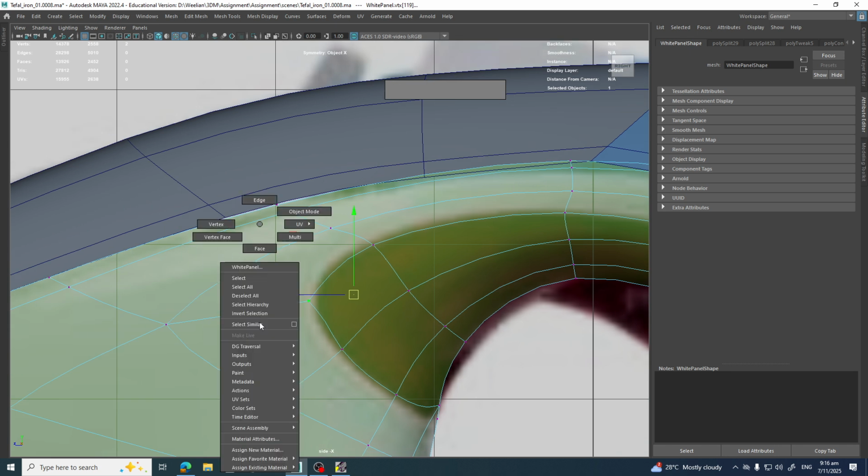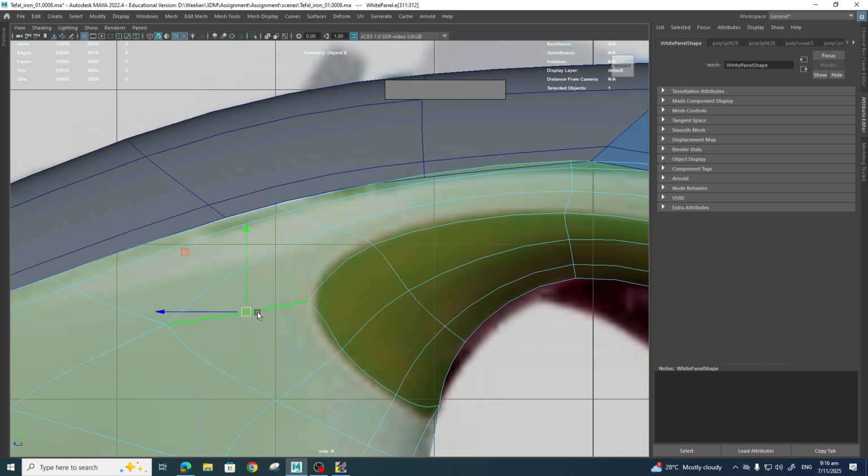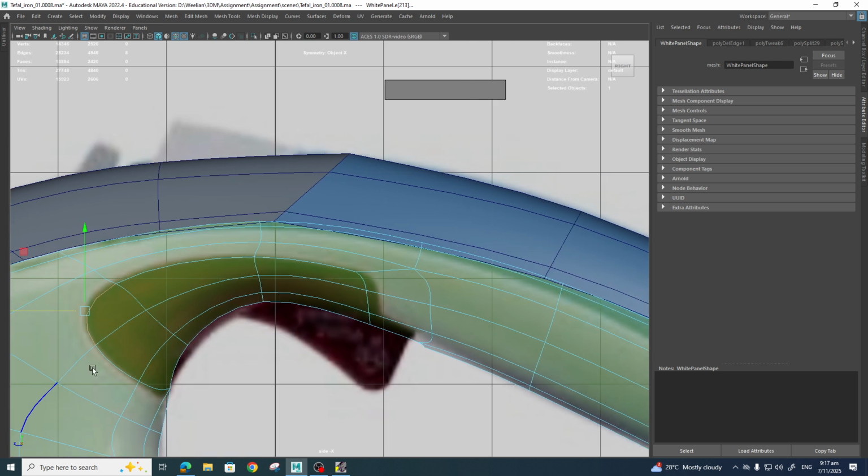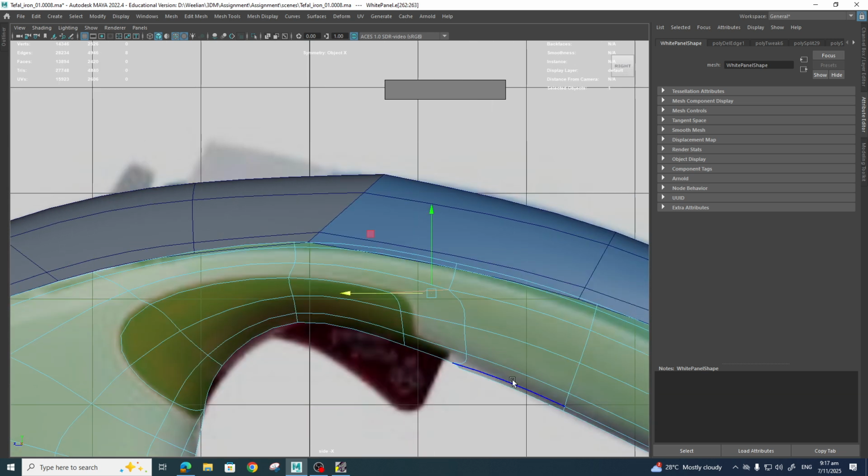So maybe I will delete away this. I have to do a control delete so that the vertex here is not selected. For this one here, just to get this curve right, I will deliberately give it a multi-sided face over here. Same for this one. Control delete, and let's see how far I can get this to match. In fact, I don't think this one is working very well, so I'm going to undo that and just slide this back a little bit.